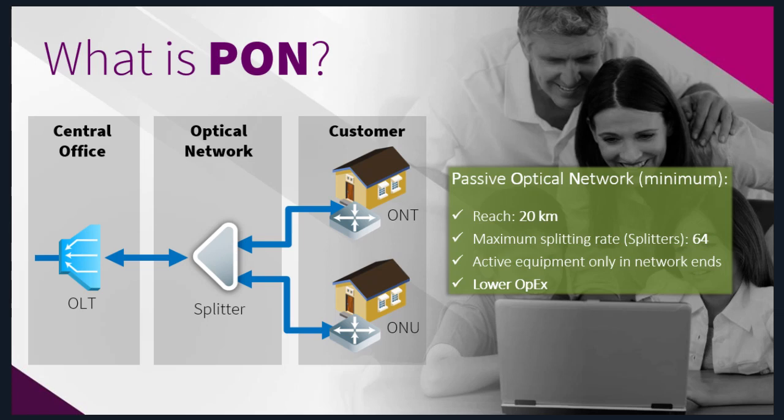And those customers will have just one fiber reaching their homes. And those unique fibers are not from the central office. They are from a midpoint in the network. So the infrastructure from the central office to this distribution network, as in the examples here, is reduced dramatically. So we have just one fiber now, roughly, for up to 64 and from 64 up to 128 customers.